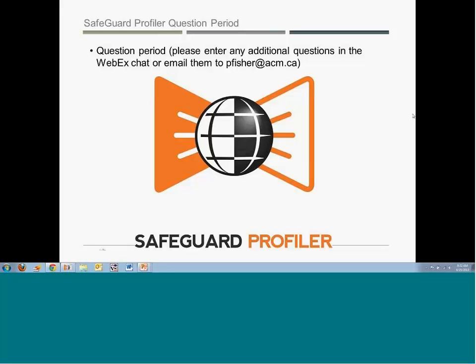And the next question is, can Profiler identify common cause failures? In terms of a LOPA, that is going to be up to the team and the facilitator. Unfortunately, there's no real way to automatically identify common cause failures. The people in the room in your LOPA session are the ones who best know what common causes are. There's no way to tell that automatically.